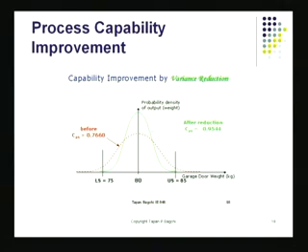There are a couple of ways to do it. Suppose your process had the distribution that was like the red dotted line. This was the distribution of the output coming out of your system, your machine, or whatever it was. The spec limits are shown here, and notice carefully that some tail of the old process is below the specification limit and also above the specification limit.